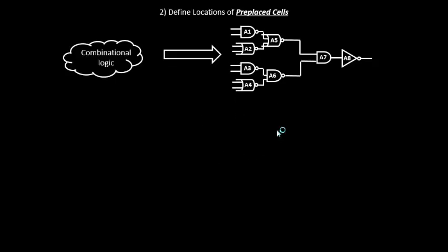Okay, so there is a way that we do not implement this circuitry every time as a part of the main circuitry. We can take this piece of the circuit out of the main circuit and implement it separately. And we can even granularize this particular circuit itself. So if this was, let's say, 100k gates, we can divide this circuit in such a fashion that you can make it 50k gates and 50k gates.